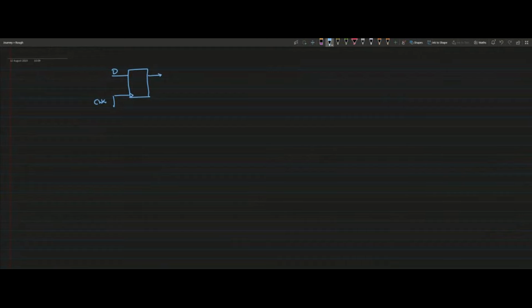After this, I will have various logical gates like AND, OR, and the signal will be going through a lot of combinational logic. It can be an adder, a subtractor, but not a sequential element in between. And here I am passing that data to another flip-flop, and this is also connected to the same clock.